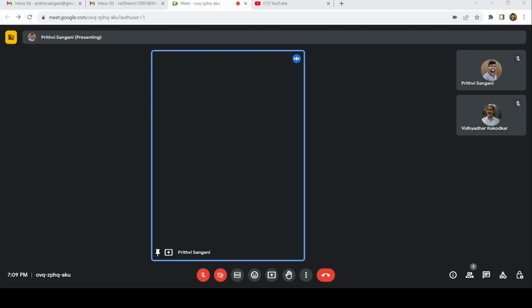What about FBD? FBC? We have FBC here. Where is it? FBC is done. Okay, sorry, FBD. FBD is nothing but FBC cos 45, square root of 2. That is going to be 10 root 2 by 10 root 2, that is going to be 10, and it is in compression. So FBD is going to be compressed, so this is going to be compressed 10.